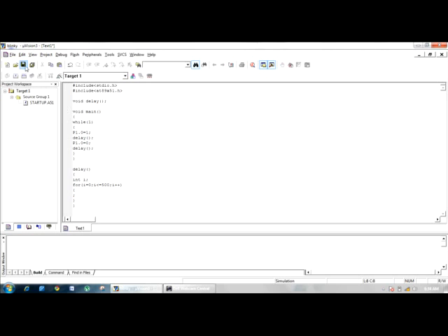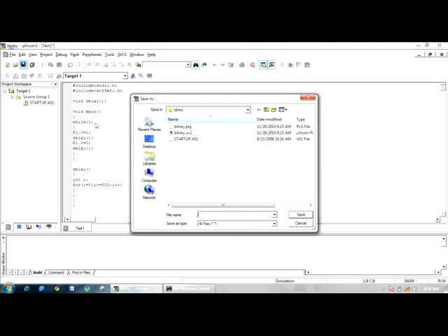See what happens. Click save. You get the folder in which you have saved your project. Save the title of the C file in the same name as your project to avoid confusion. So use Blinky. And don't forget to specify the extension as .c. This is not a C++ program, this is a C program, an embedded C program, so we are giving blinky.c.